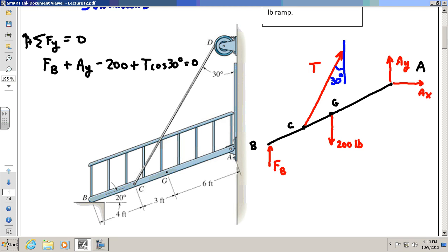That's the point I'm making by going through this exercise: sometimes you can just blindly throw forces on there, and that's okay, we're learning, but sometimes you have to think and go, well, that's true, but I have too many unknowns, what's going on here? Well, if you have enough force for this cable to lift this ramp, then there's no more contact here. As soon as you lift this up like 1 millimeter off the ground, we ignore it. We just take it out of the equations. Oops, too many things out. Let me put this back in.